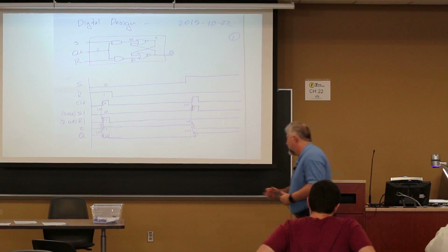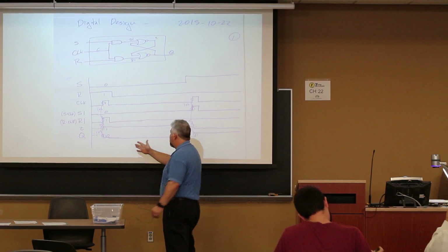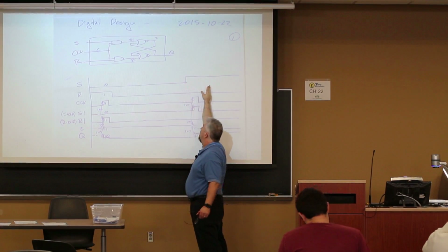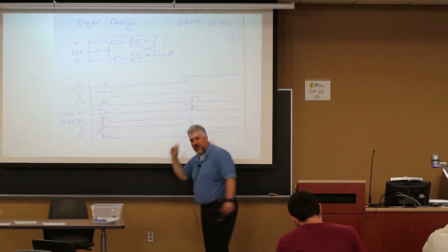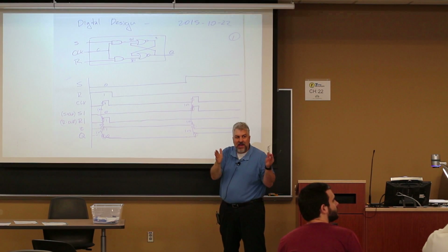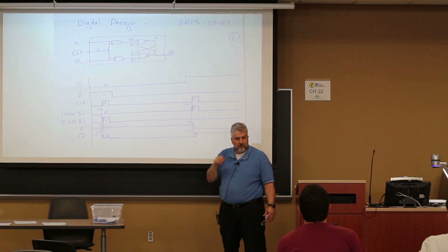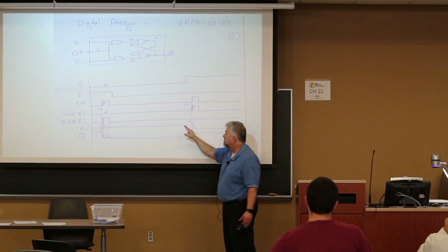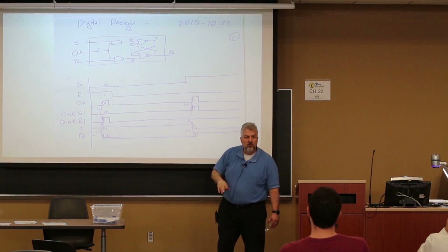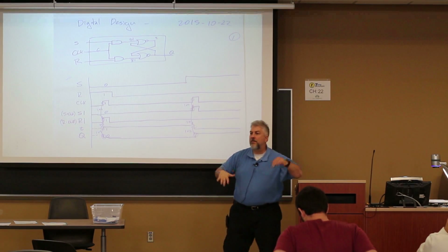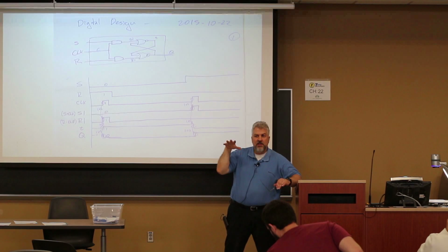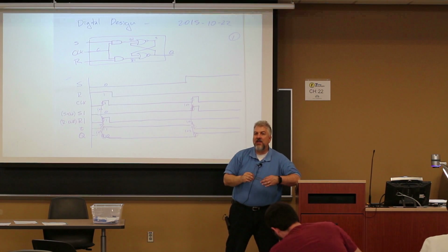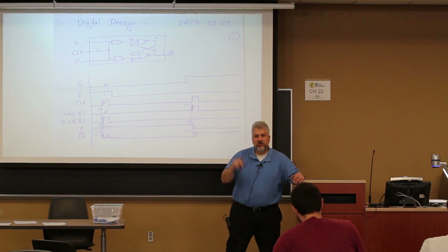So here's the point. After we have this steady state, I wanted you to realize that even though you have S and you raised it, and you notice in my example I gave you, there was some time between S and the clock, right? Because typically, everything in digital circuits is based on that clock. You want the input signals, the combinational logic-ish type signals, to be steady. In other words, to not be wandering around. And then you give it the clock to record that.